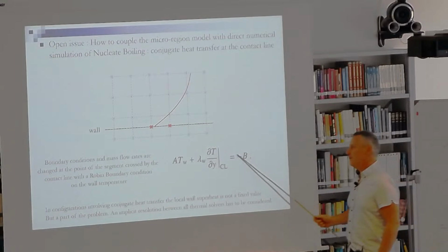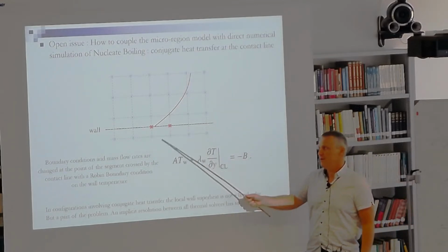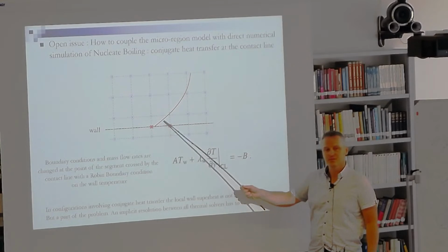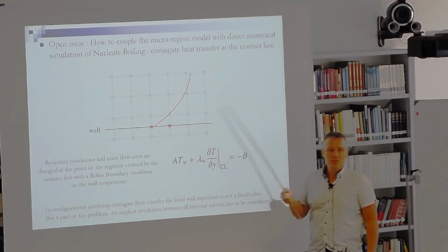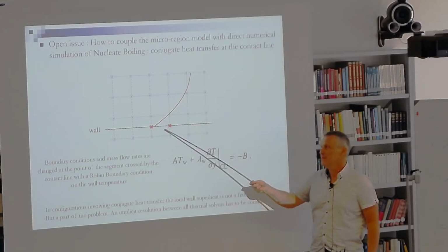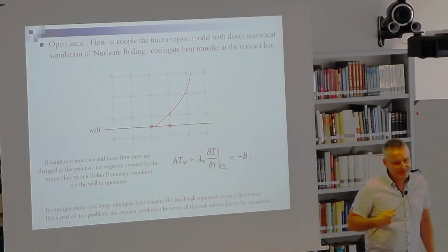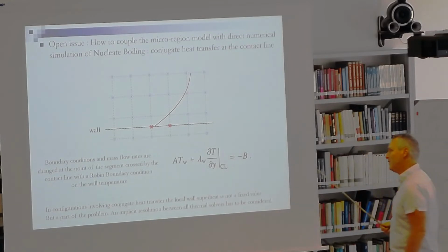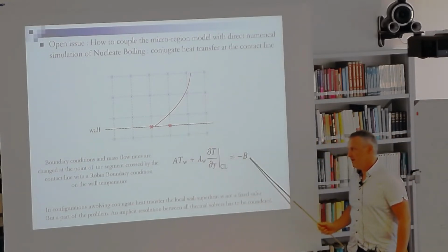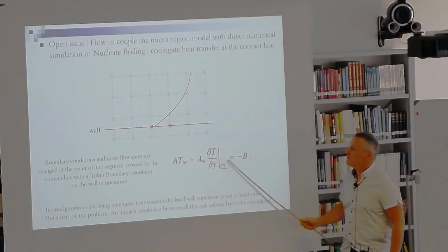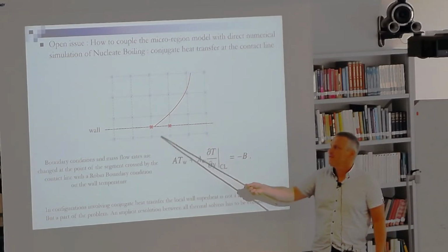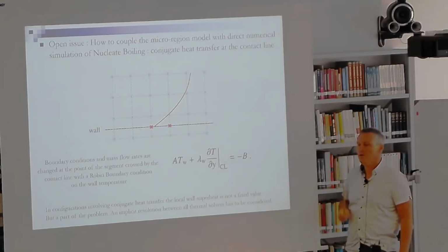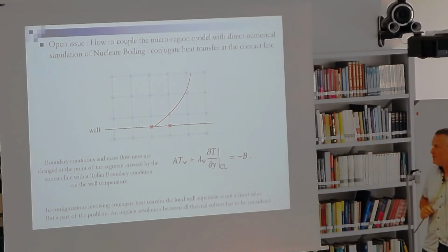But if we do not do this implicit coupling, but just try to equalize the flux between the two systems, the interface will tend to thermalize the wall, which will tend to take the saturation temperature, and this will result in a vanishing effect of the microregion, but this is artificial. Only an implicit coupling that implicitly enforces the microregion flux when solving the heat transfer in this mesh enables us to account for this microregion effect.